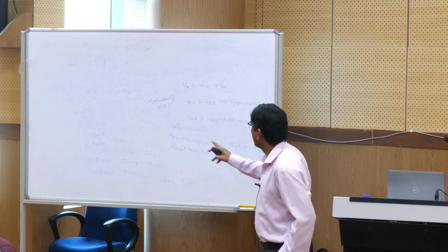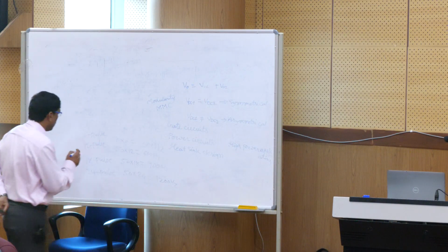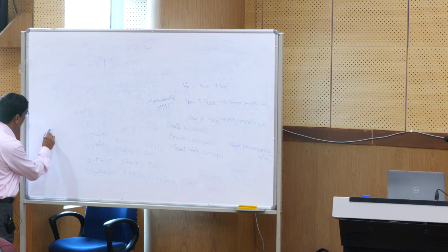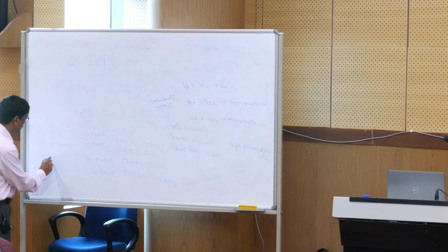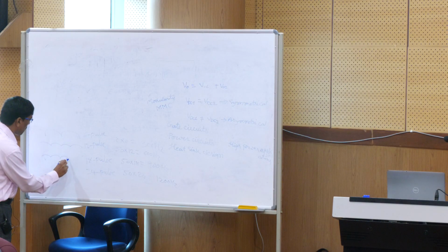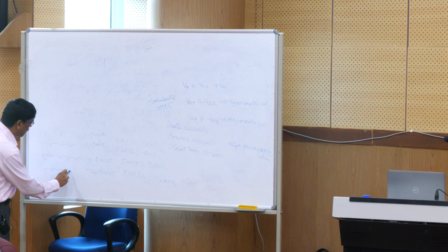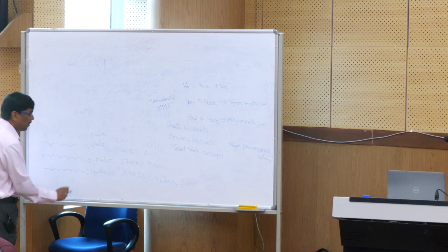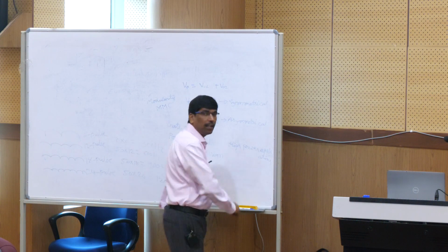Even then, if you take the 6 pulse, the output will be more like this, and in this case more number of pulses will be there, and here still smaller, and when it comes to 24 pulse it will be still smaller, but you can't get pure DC.